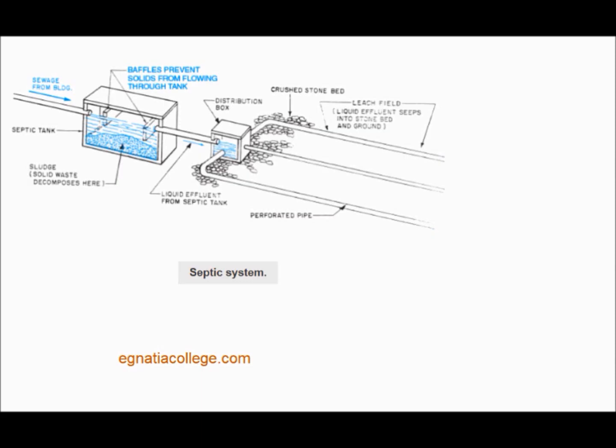The septic tank holds the solid waste while it is decomposed by bacterial action. The liquids pass through the baffles and flow out of the tank to the distribution box. The distribution box, DB, diverts the liquid into leach lines. These perforated plastic or loose-fitting tile lines allow the liquid to be absorbed by the surrounding soil. The liquid gradually evaporates from or drains through the soil. The drain field, where the leach lines are laid, is usually made of a layer of crushed stone.